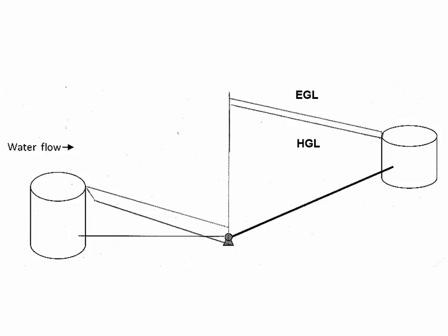Question? Yeah. Do my EGL and HGL have to touch the pump? No, they don't. So the question was, does the line have to touch the pump? And no, it doesn't. In this case, it just did because I started drawing the lines at a certain slope, and that's where it ended up. The only thing that you have to have is a big jump up because of the pump. You have to have the lines closer together here because this is a larger diameter pipe. It should be less steep. And then it terminates at the water surface for the HGL.